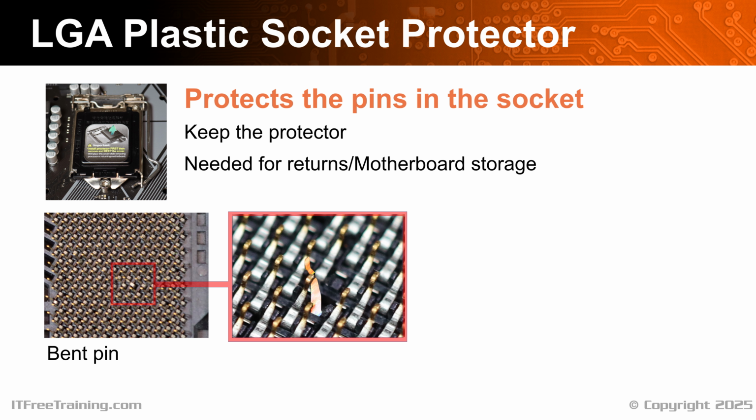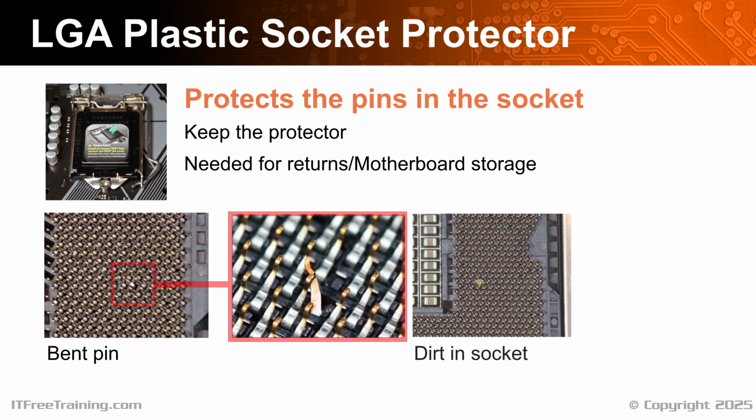Even if just one pin can't connect to the CPU, this can make the CPU completely unusable. If your CPU still works, it may be unstable or not fully functional. Generally, if a pin is damaged, it means the motherboard will need to be replaced. The socket is also subject to dust and dirt.